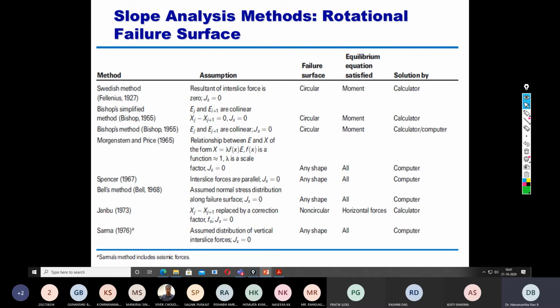Okay, so try to understand, most of the failures can happen by picking even the wrong method of analysis. If you look carefully, if you truly understand as a geotechnical engineer, if you pick the wrong method, then, say for example, you are on the verge. When I use, say, the Swedish method, my factor of safety is say 1.1 or 1.2. But if I use another method, say the Spencer method, and I get a factor of safety of 0.95, it indicates that it will fail.